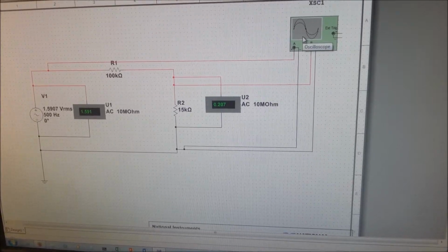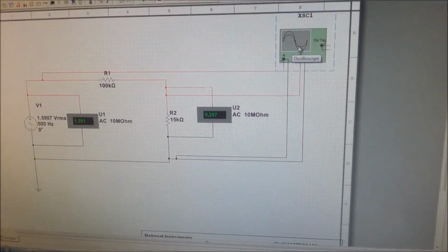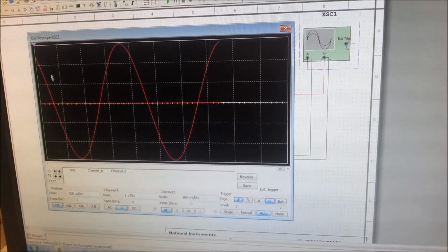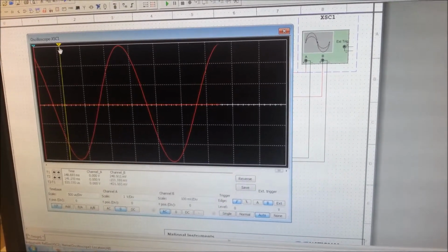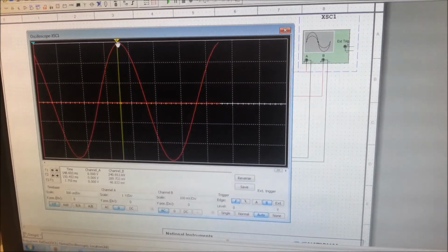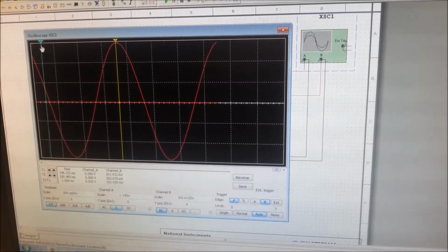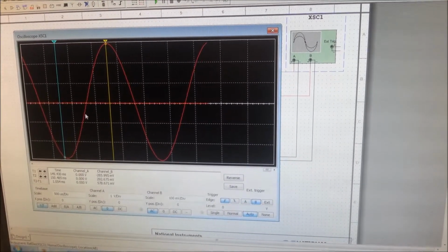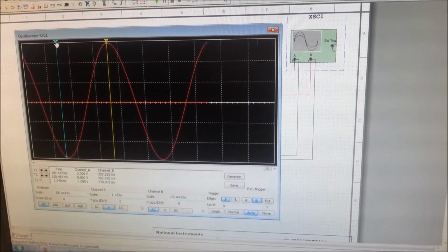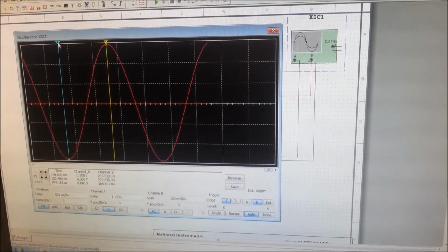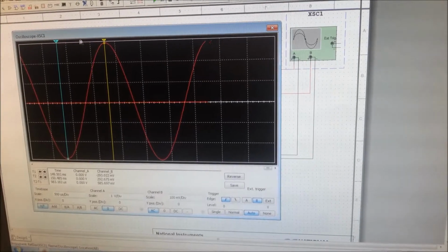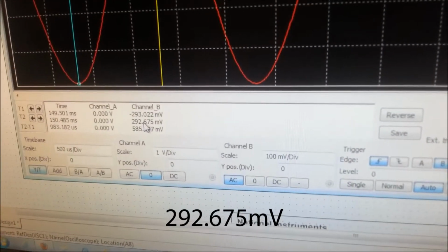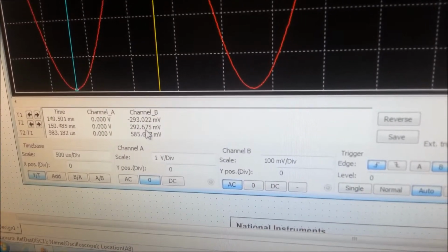which is, now we double click on our oscilloscope and we can clearly see, make sure you have B selected. That's our B input that we're working with right now. Grab our sliders, try to put one as close to your maximum, put the other closer to your minimum, and let me move this a little bit over. Make sure again it's on your peaks and your valleys, and you can clearly see there that that's our answer.